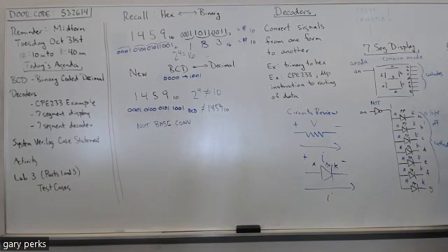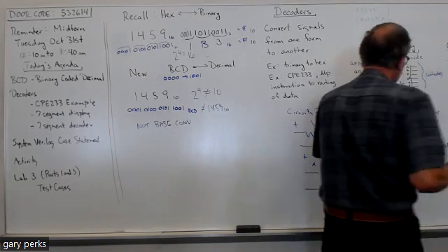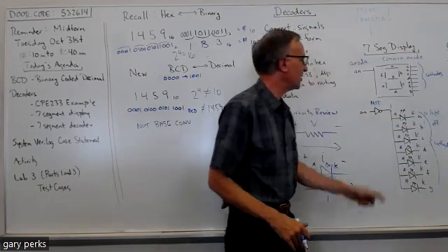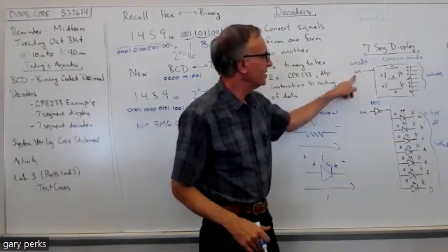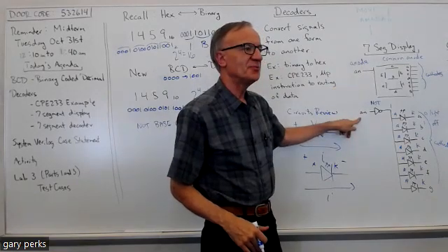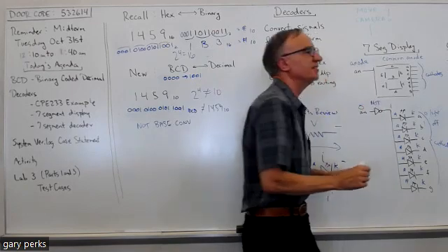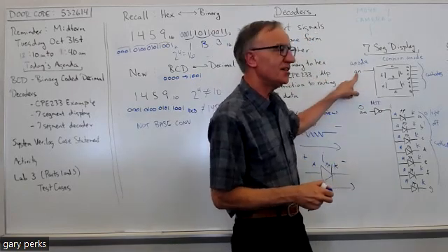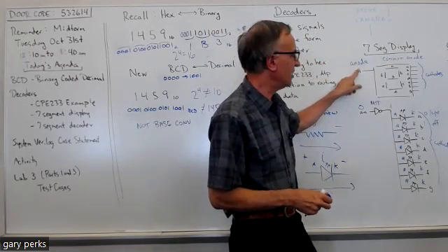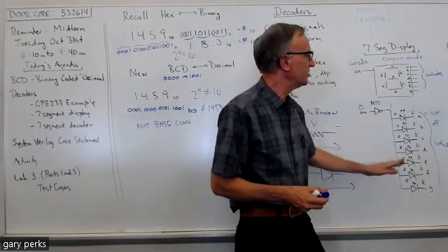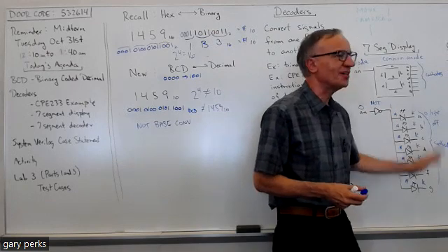So if I need a 1 on this common anode in order for this display to work, well, what does this AN pin have to be? What value? Yeah, it's got to be a 0. And so you've got to put a 0 on this AN input in order to put a 1 on the common anode node, so that what we just discussed will work.